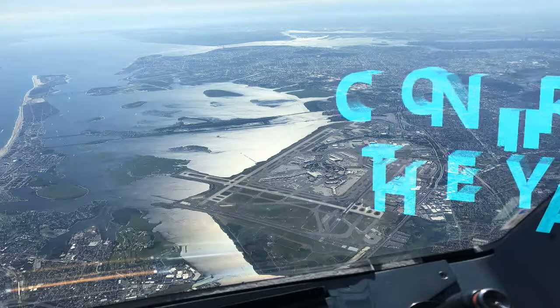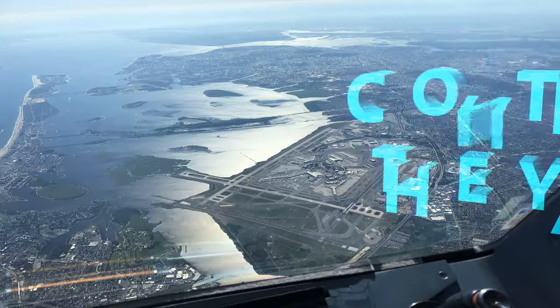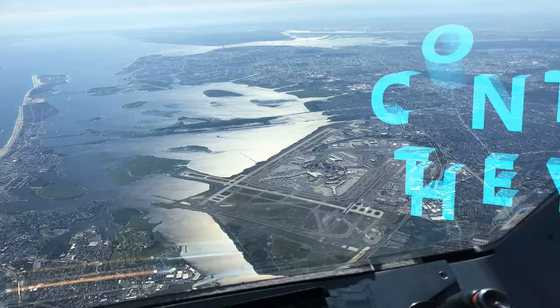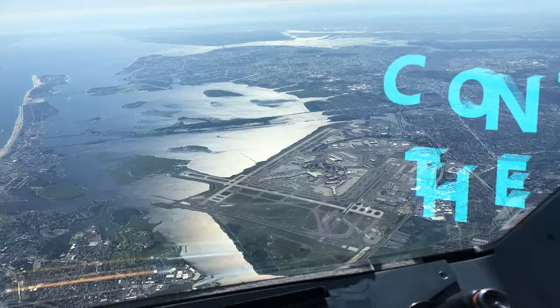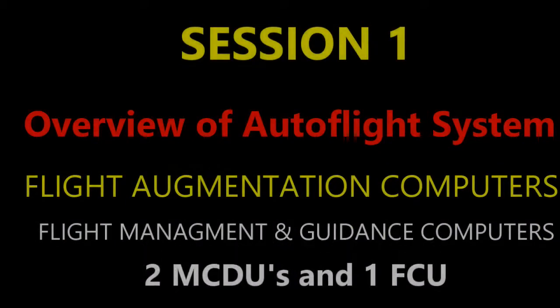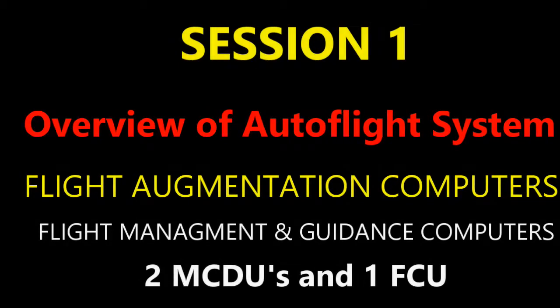Okay. Now, besides the 4 computers that I mentioned right from the beginning, we also have 2 MCDUs. So we have our multi-purpose control and display units, and we also have 1 flight control unit. Okay, so 2 MCDUs and 1 flight control unit. And just a quick note, the 1 flight control unit is your short-term interface between the crew and the other computer that I'm going to cover, which is your FMGC, which are your flight management and guidance computers.